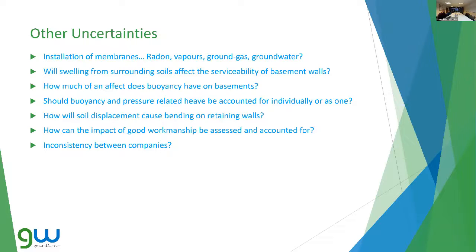But a really important thing to say is how do we know the impact of good workmanship, and how is that being assessed? How is it being accounted for? Because good workmanship is so important in order to construct and excavate a basement and limit movements to acceptable limits, or at least the limits that were anticipated. If there's not proper dewatering or propping up, then there could be catastrophic effects.